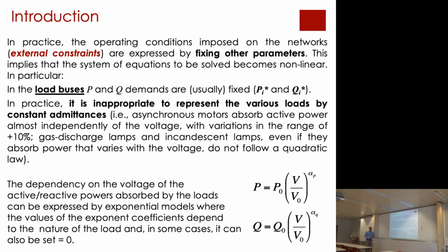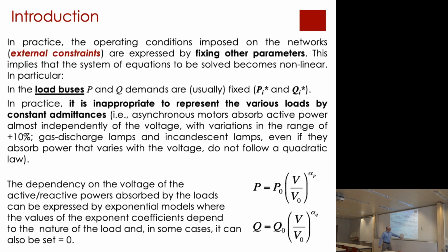Okay? This means that you can fix P0 and Q0, but then you have to bring these two equations into the load flow problem, since they will slightly change the active and reactive power that the loads absorb, different from P0 and Q0, according to the voltage that you're going to get in the solution of the load flow problem. Okay?